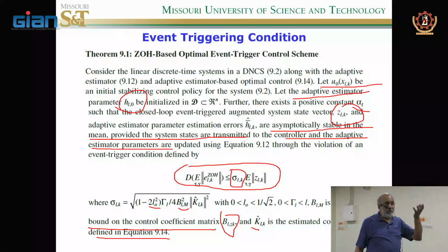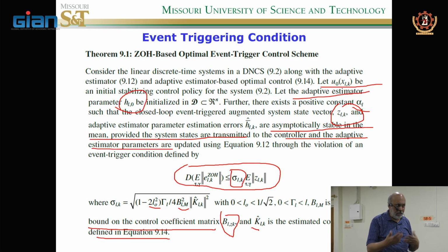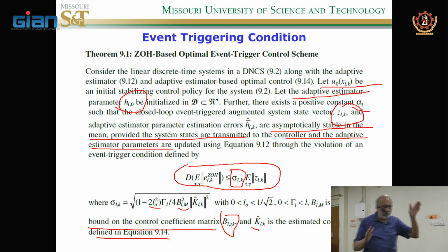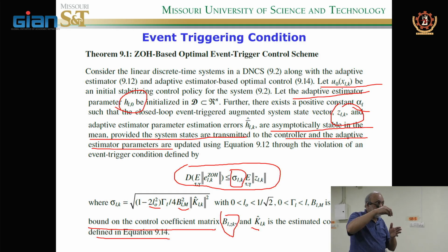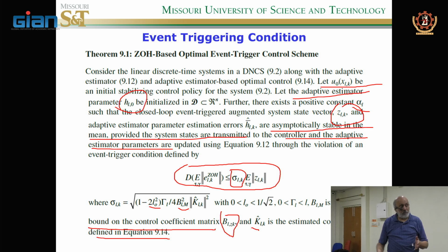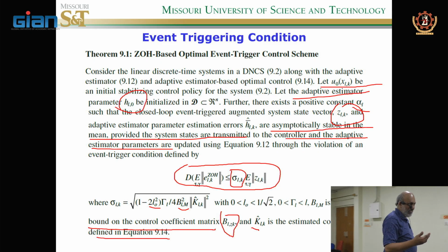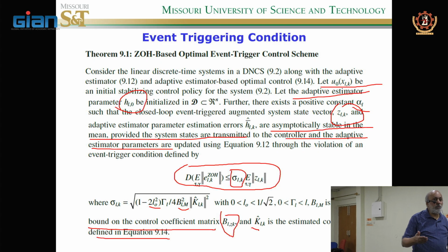As a consequence, the dynamics become uncertain. And therefore, you use Q-learning or a neural network to design the controller. That's what we did. But then we also realized that we haven't really spent time on the network side of it. How do I reduce the random delay? How do I reduce the packet losses? That's what the next step is. So how do I do that? I'm doing it through scheduling.